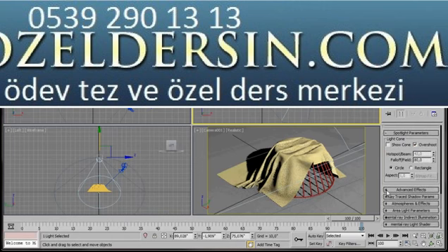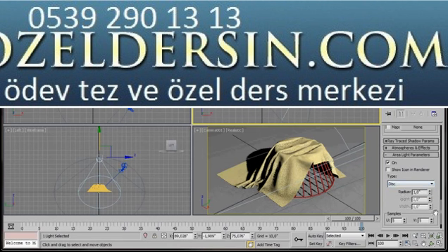Now we'll carry on scrolling down. In advanced effects, make sure we have diffuse and specular turned on. Now we can go to the area light parameters. Here in type, let's select disk. The radius and the samples, they're going to soften our shadows. So at the moment we're just going to do a trial test. Let's type in a radius of 20 and samples, we'll put in a U of 10 and a V of 10, but we might come back a little bit later on and change this.